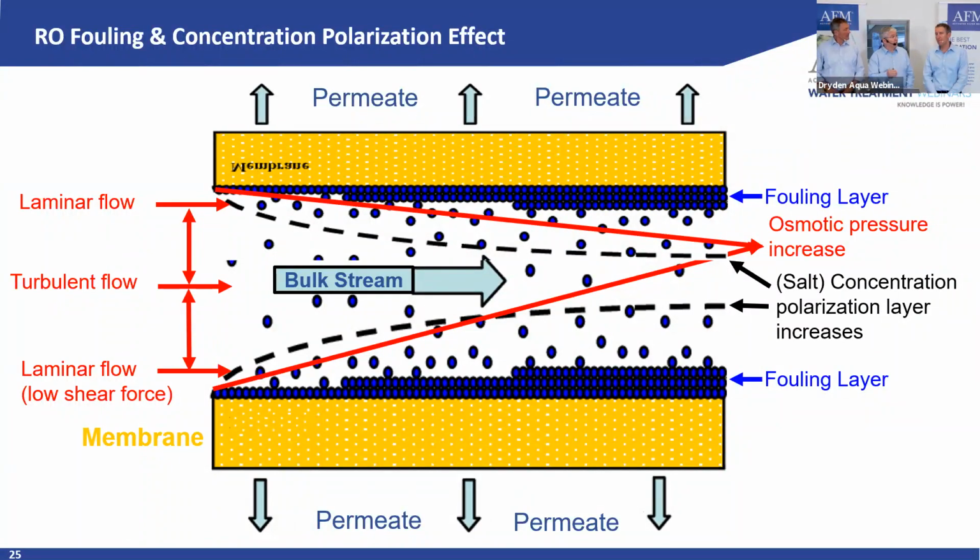We talk about reverse osmosis. So that's where the word osmotic comes in. We actually do the reverse of it. That means we need to overcome the natural osmotic pressure. What we do in this process is generate a higher concentration of salts. That means a higher natural osmotic pressure. So we need more pressure, more force, more energy to push the water through the membranes.